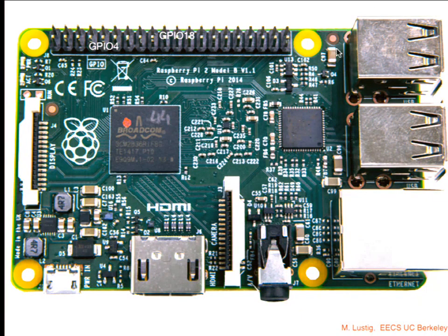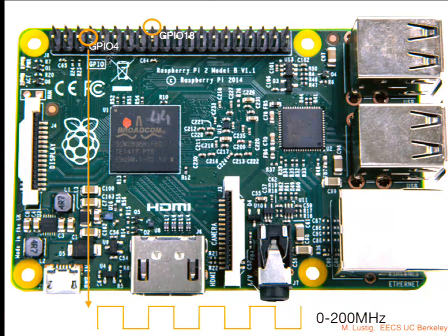Okay. So this is the stuff that people who like to make things would use. And one of the things that they use is those GPIO ports. GPIO, general purpose I/O ports, that you can control to switch on lights and so on and so forth. There are 2 ports that are actually interesting here that I want to point out. One of them is port 4, and the other one is port 18. As it turns out, these are connected to a programmable PLL. Who does not know what a PLL means? Okay. A PLL is what's called a phase locked loop. Basically, it generates a frequency.